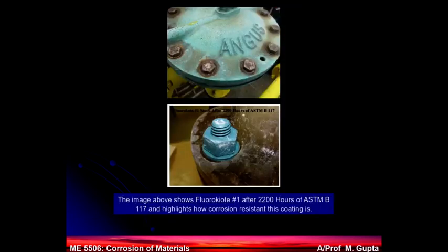And here is a situation when you have this nuts and bolts structure and they immediately give a galvanic corrosion. Because they may be different types of material, that's why the corrosion is only in these bolts here. So that is where we have to be aware of what are the good coatings here.